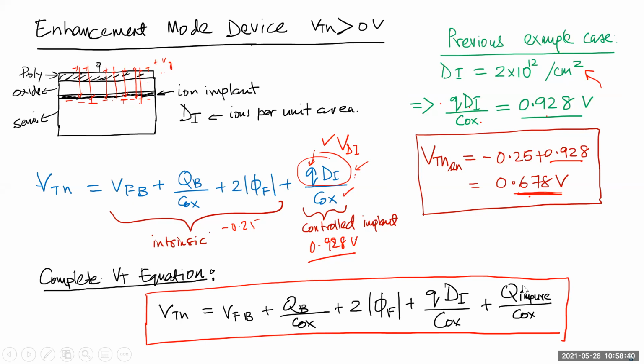Plus, like I said, when these things are fabricated, since the silicon dioxide is going through a lot of this gaseous process, growing over an interface and all that, there are a lot of impurities, mostly at the interface between silicon and oxide, as well as inside, because these are usually grown layer by layer.